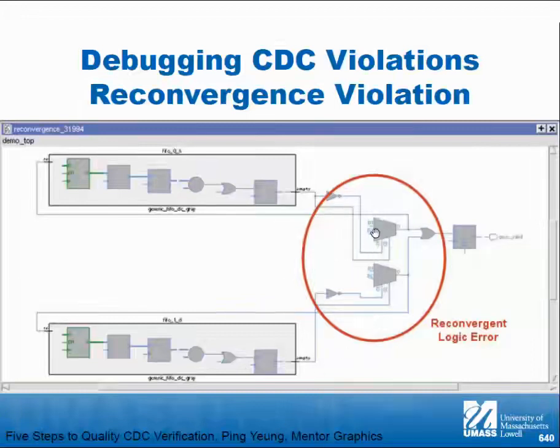This is the first time I've explicitly shown this. The other cases, it's all been happy, a flip-flop that goes to two flip-flops. It has to be that. It has to be a flip-flop going to flip-flops, no logic in between, especially logic that's fed by potentially two different clock domains into a third clock domain.